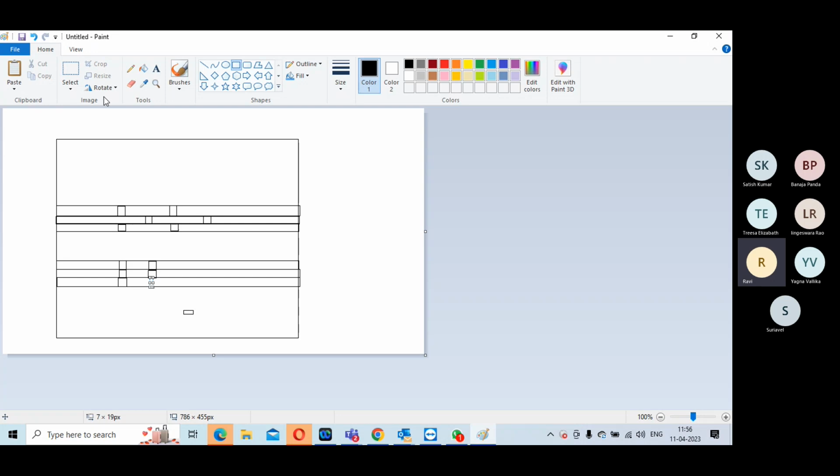In fills, there are two things, pre-fill and post fill. The tap cell and end cap are all pre-fill. That means before you do your placement, you have to add all the pre-fills. It has the priority. Post fill is after you have done routing and everything, then you are going to patch the cells. Post fill will have different varieties of fillers. Pre-fill won't have that. Pre-fill you will have tap cell and end cap cell. Post fill will have decap and other filler cells.